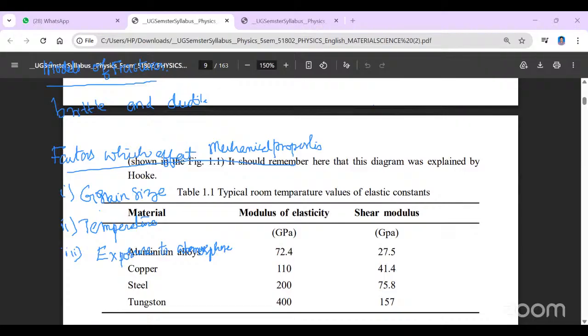So the presence of chloride in a marine atmosphere, that means where the sea is present, increases the conductivity of the liquid layer which is in contact with the metal surface. So when we go to the marine atmosphere, the presence of chloride increases, and therefore the resistivity decreases in the presence of this air moisture.